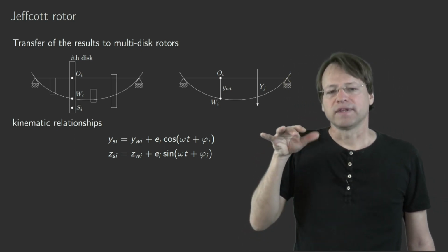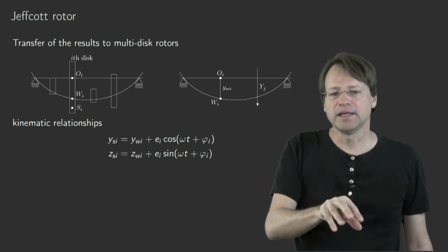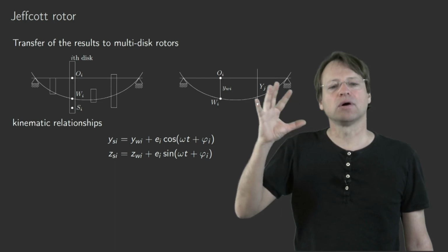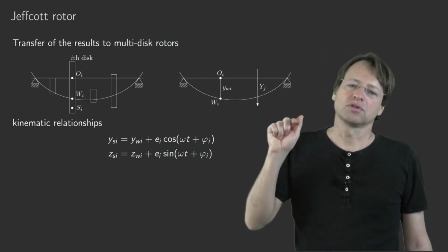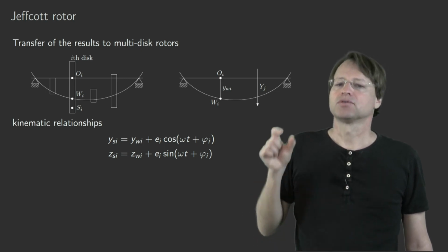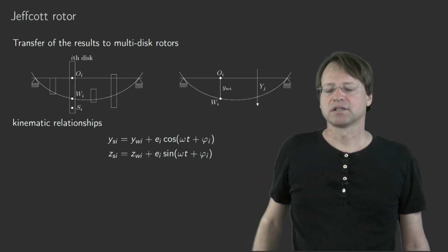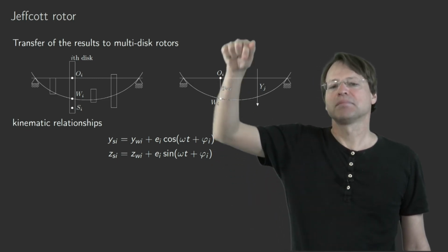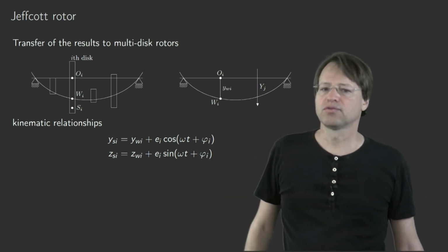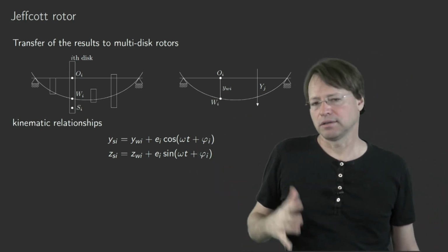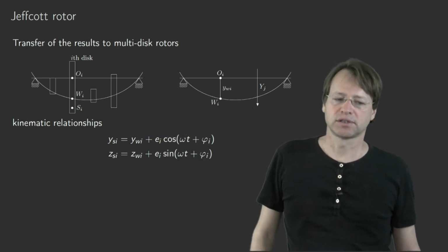And finally, this would be one load case, and due to the fact that we are considering a linear elasticity, so we know that our problem is described by linear equations, we can use the superposition principle. So the total displacement at one disc will be influenced by all the other forces, which are then not the unit forces, but the concrete or realistic forces at the position of all the other discs.